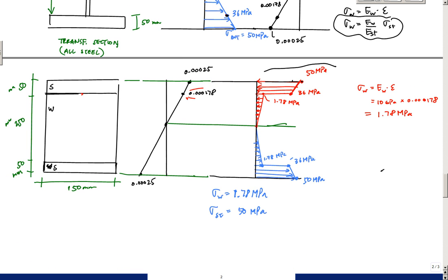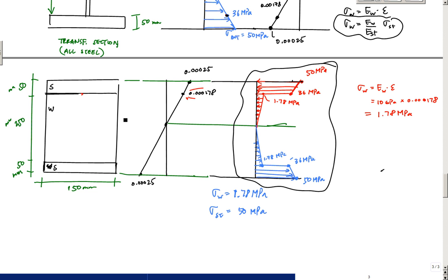Okay, so this was a little bit more detail. Normally, you're not asked in problems to draw the strain profile, but drawing the strain profile is really useful, especially if you do any kind of experimentation, because really most of the time all you have to measure things are strain gauges and displacement transducers. And the strain gauges are used the most in terms of taking measurements off of a structure or a material.